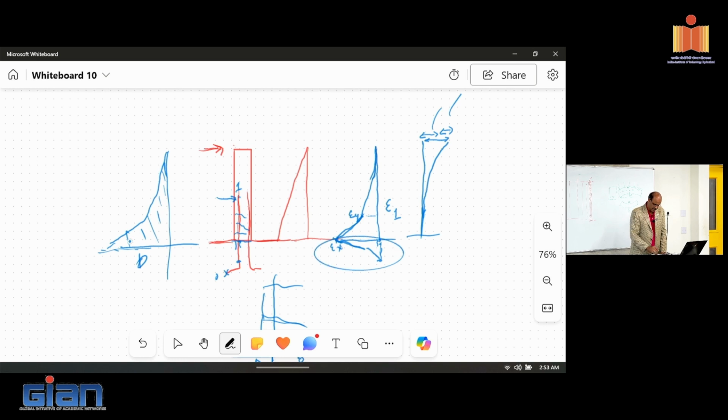So the displacement is due to this curvature here, which is what we normally account for. So if you model in finite element, for example, you will actually account for this value. This value you will not account for because they don't model penetration. So your analysis results will be off by 30% because you're not accounting for it. When you don't account for the penetration effect, if you do finite element analysis, you will find the strains right underneath the foundation get to zero pretty quickly, which, based on what we discussed so far, should not be zero. It should be a pretty high value.